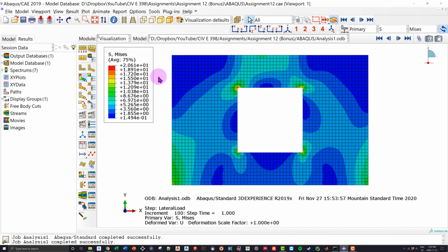If it's 25 MPa, then yes, they are. Now we move on to the second thing, which is asking, did the wall exhibit enough stiffness? Remember, when I apply the load here, I want to make sure that it takes a lot of load to apply 3 millimeters. Think of when you hold a ruler and push it with your finger. It doesn't take a lot of load for that ruler to bend.